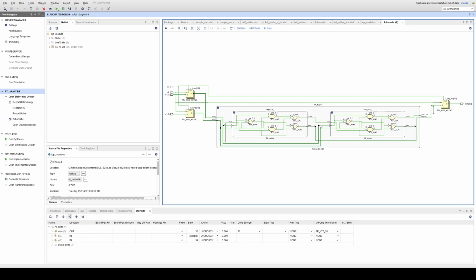So in order to actually test our FPGA modules, we must create something called test benches. A test bench contains an instantiation of a design module, to basically build simulations of inputs and outputs to test the behavior of our code.